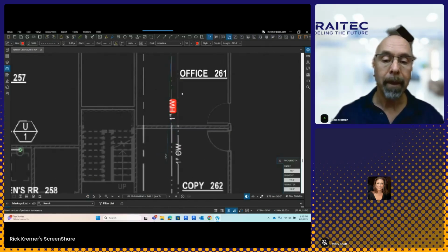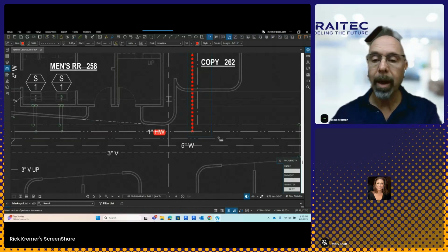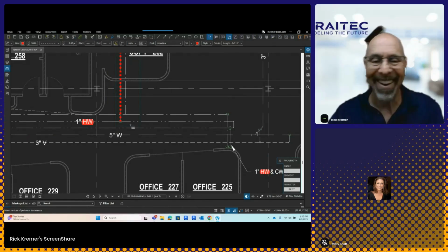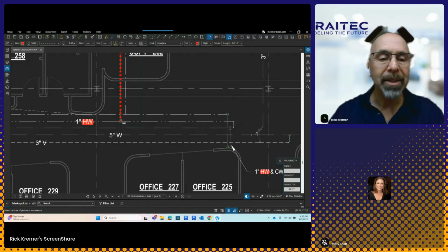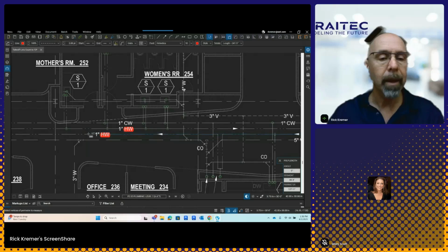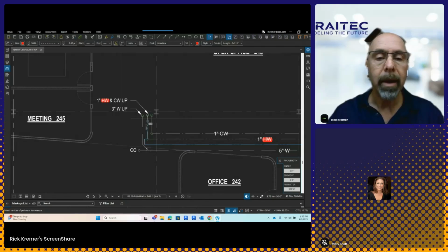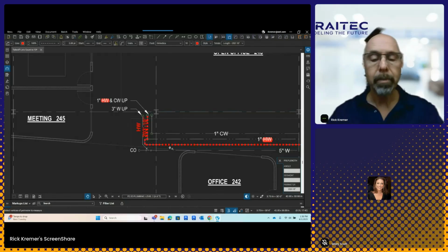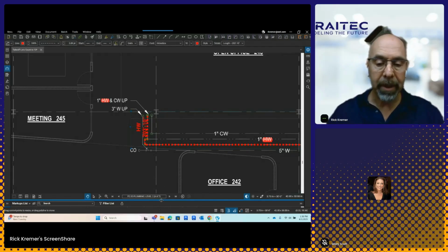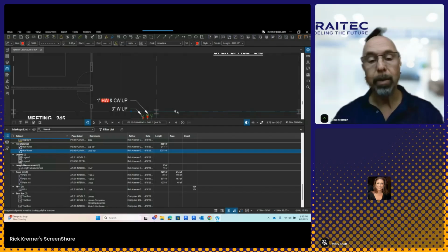And I click here and I follow it down. Boom. I'm already in hot water. So from here, I'm going to say this continues over here and goes to here and to here, and it follows all the way across. I'm just going to go from here and keep clicking. And let's say it stops right here and it goes to this point. Boom. When I select it, that particular object, when I look at it, is individual segments, and the total length is 238 feet. I want to continue with my calculations.